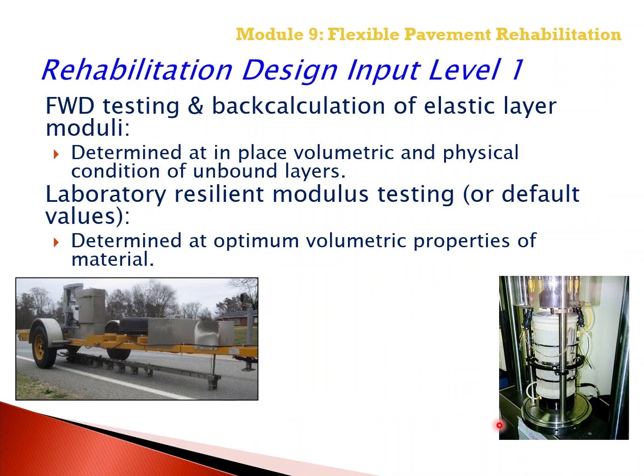Now moving on to back calculating the layer moduli for unbound layers. In other words, FWD testing and back calculation of elastic layer moduli for defining the in-place elastic modulus of the unbound layers. Two important items. The moduli are determined at the in-place volumetric and physical condition of the unbound layers.